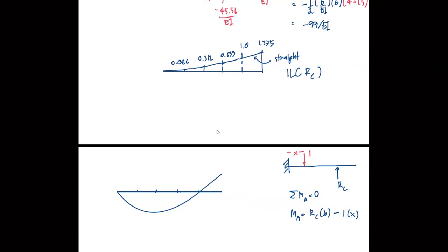Looks good. The influence line should look like that. And this is the influence line of moment at A, of course. Calculating the values from this equation, you should have the values here equal to minus 0.984. Here is minus 0.125. This is minus 0.702. At C, it has to be 0 because that's when the load is at C.